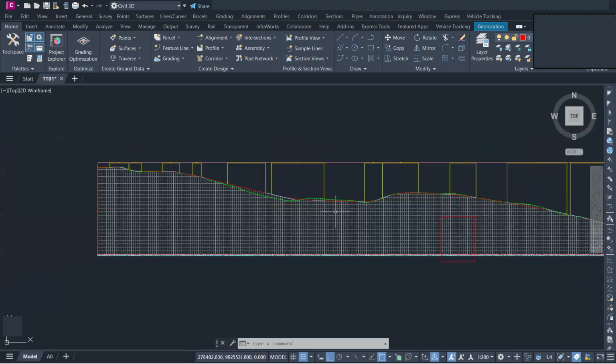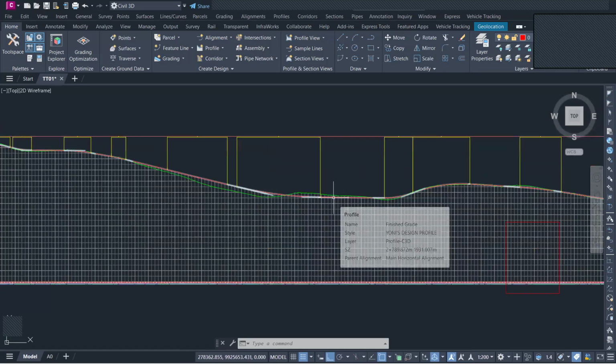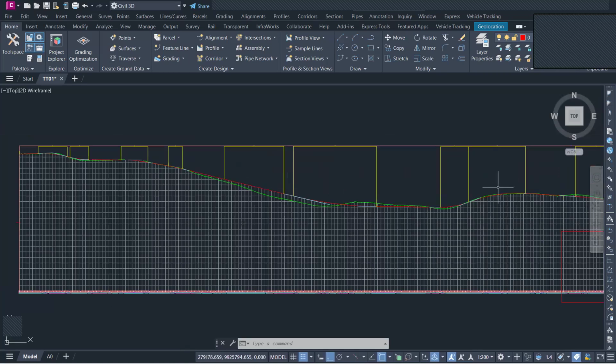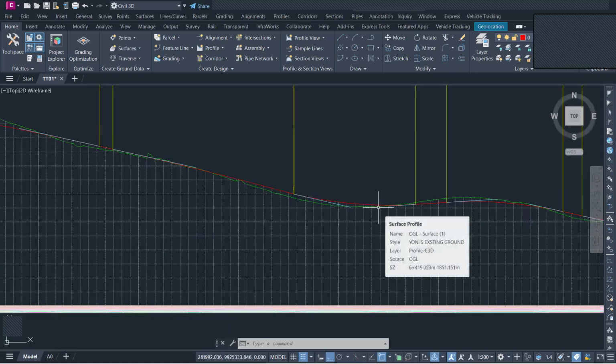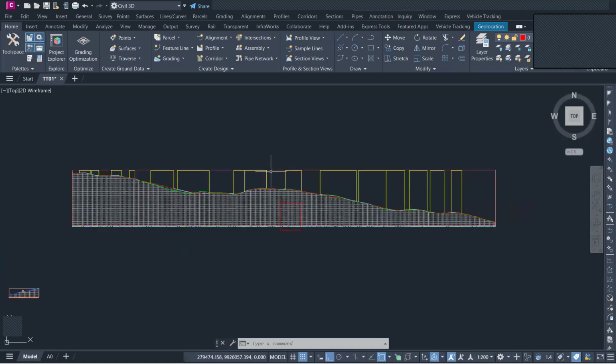Now, how do you determine the location? It is obvious. You need a culvert at this point to drain water. You're having water coming down from the left-hand side, and you're having water coming down from the right-hand side. So you need to position a culvert somewhere here. Same thing again, it's common sense. You will need another culvert here. All of this water will be draining to this point and these others.